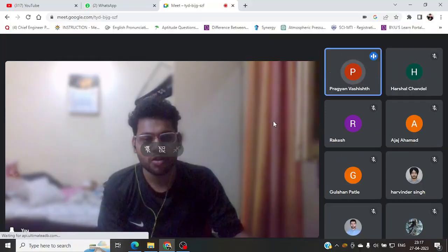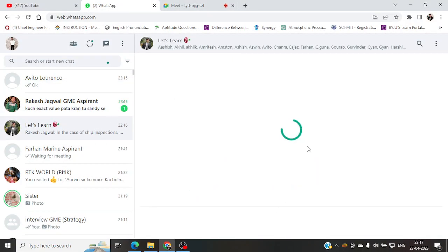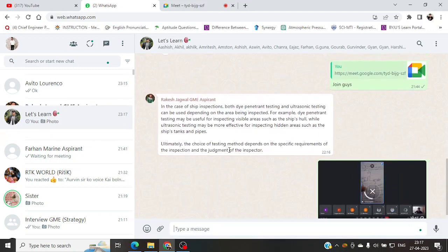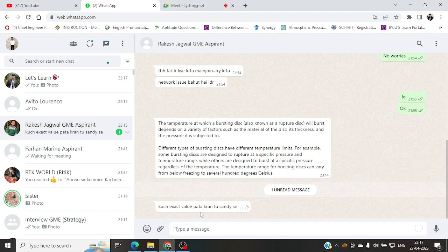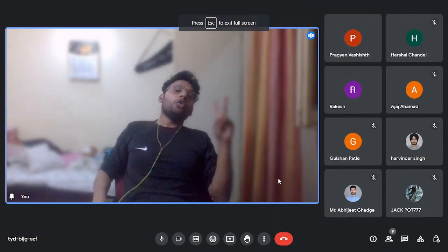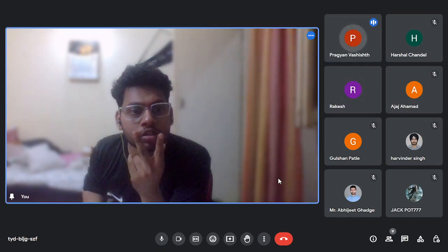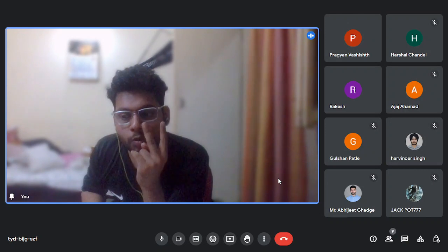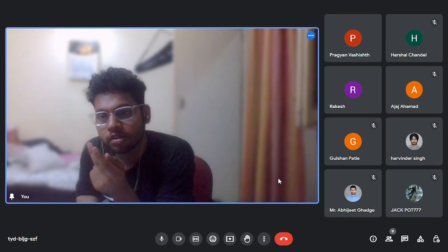On ships, we have to maintain a level of security, so we do not allow the water level to go that low. The fusible plug self-activates at a safe water limit. I heard from someone that there is a low water level shutdown. Yes, I've also heard. Don't say both things: either say low water level shutdown, or say fusible plug.